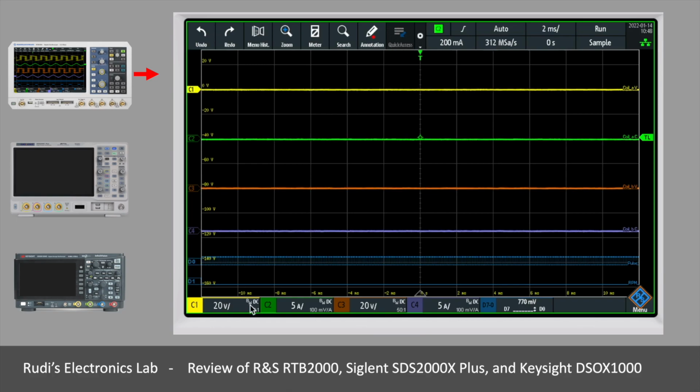Down here for each of the channels we see the probe settings, and we can see here this is a differential probe, which is a 10:1 probe. I've set it to 20 megahertz bandwidth limiting because it's actually low frequencies I'm measuring today, and it's DC coupled. Over here we see a current probe, so we probably see it being configured at 100 millivolts per ampere, also bandwidth limited.